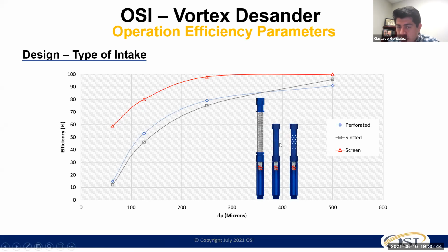And then when you're dealing with just a traditional desander, you don't see that effect. It's just a big entry point where there is no regulation. All the sand goes in at once. At least with the screen, you're able to actually select how much sand you want to reject and what range of particle sizes you're going to allow to come inside the system, as long as it's smaller than 180 microns or 200 microns. It will be based on the design that you're approaching, and that's what is going to keep your efficiency for that sand management.